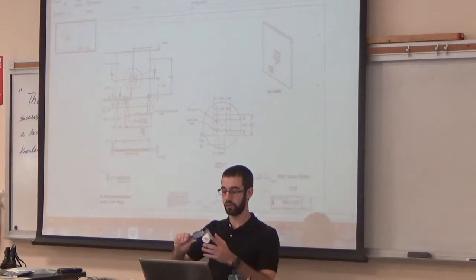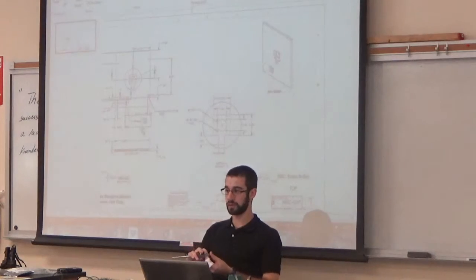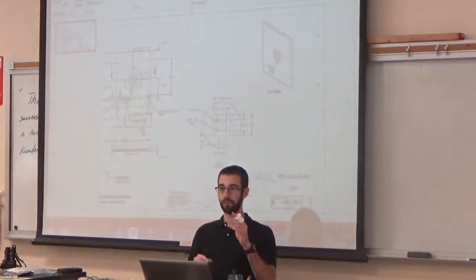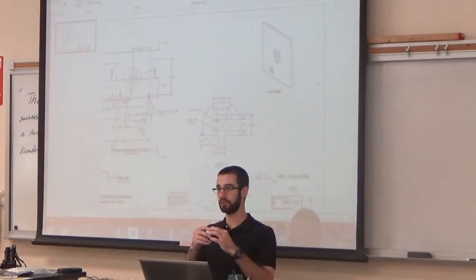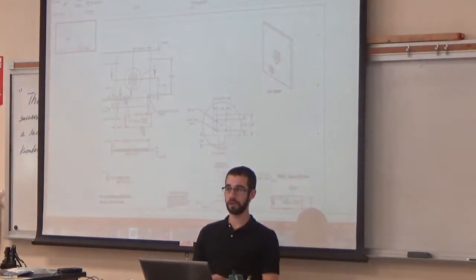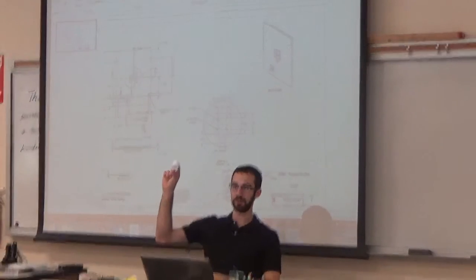And so you'll do this a couple times. Typically, when you have a lot of parts, you'll do statistical analysis on your part. Over like 1,000 of these, you'll take out 10, 20 of them, measure them, make sure they're all in spec. That's important because, anyone have a guess what this is? It's okay if you don't.